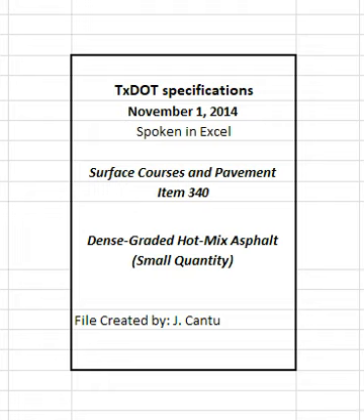The engineer will use the guidelines in Table 12 to determine the compacted lift thickness of each layer when multiple lifts are required. The thickness determined is based on the rate of 1/10 pound/square yard for each inch of pavement unless otherwise shown on the plans. Table 12. Compacted lift thickness and required core height. See table in specifications.